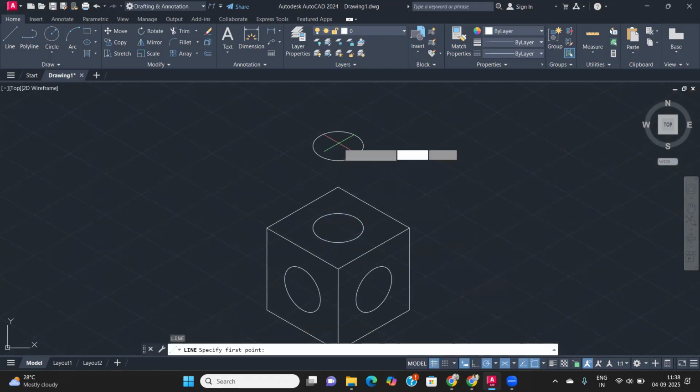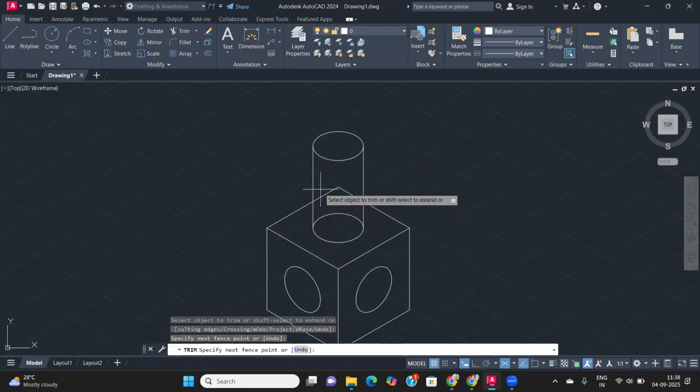Then what you do, just right here show the quadrant. This is your quadrant point. Select the quadrant and then match quadrant to quadrant. Okay. Then again, select the quadrant, not the tangent. Select your quadrant only. And after that, remove the back side faces, those you don't want to show. For this, I take the back side faces and trim them. And then this will look like your chimney, or any pipe.